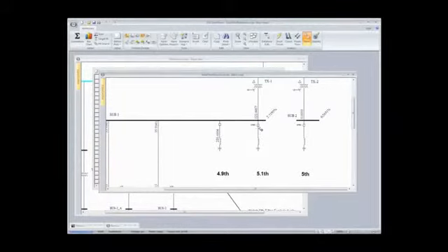But what happens is when you put them on the same bus together, it quadruples. I've seen this and I've measured it. Amazingly, we went out there, switched the filter off, and put the right size capacitor units in it. Bingo, the problem went away. All the currents dropped. So this is a real condition that you can actually experience out in the world.